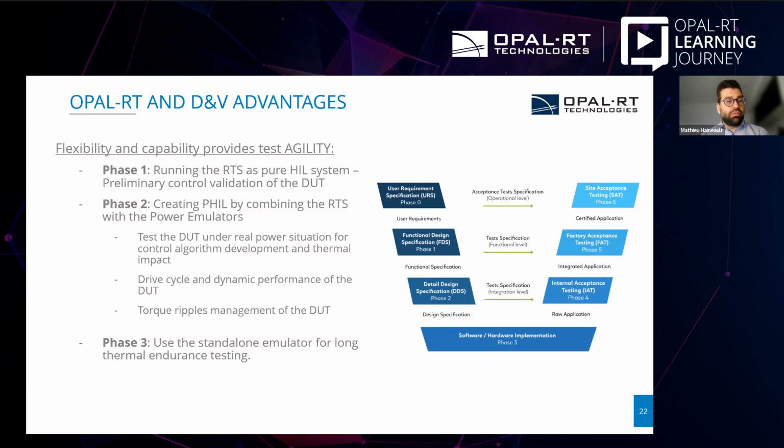Then after that, keep in mind that those tests are really good as well for testing the thermal endurance of the inverter. So you can actually, with our models and the DNV, run that for a week period if you want at full power. So it's really a nice way to do that. And since you don't have any mechanical behaviors as with a dyno, it's really more cost efficient to run those endurance tests at full power. So we can really help you towards your V cycles from the R&D to the production phase of your test.